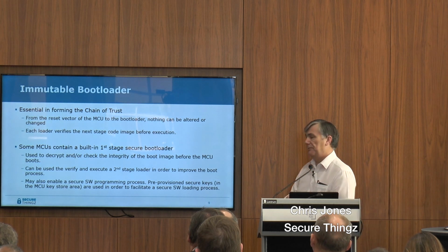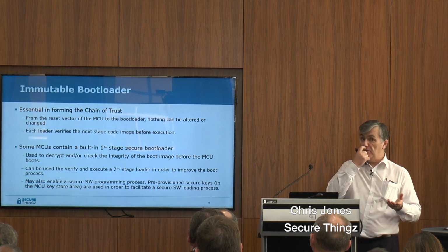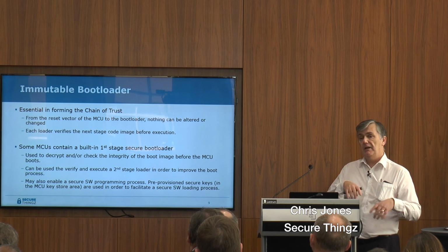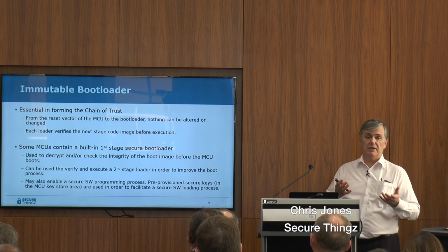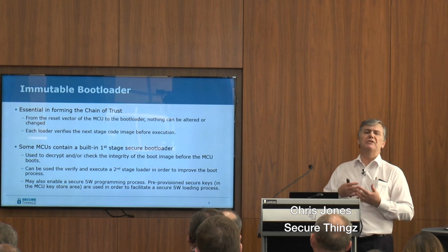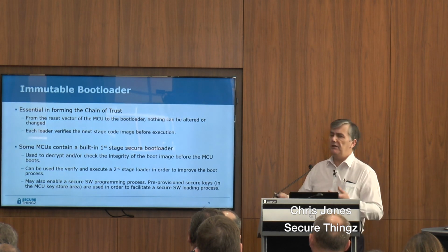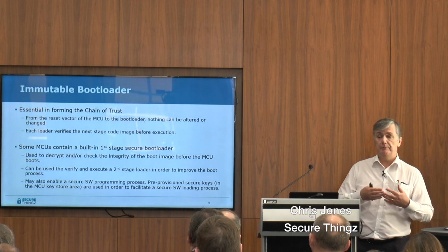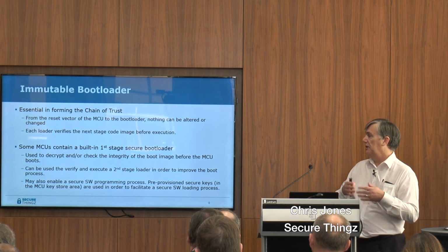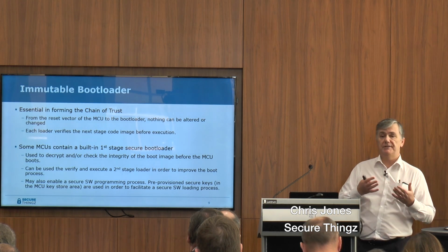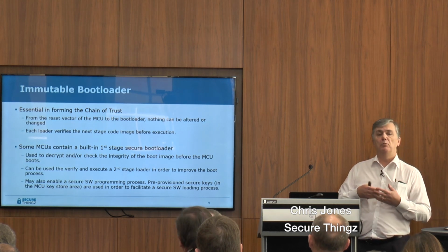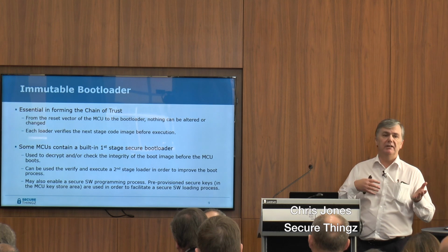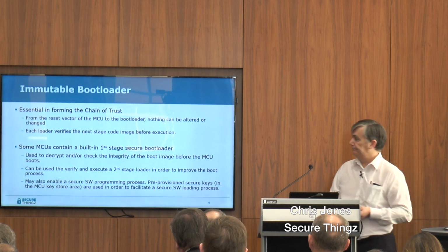So as I said here, sometimes you'll have a first stage bootloader, which will be the ROM version in the device, and then it may jump to a second stage bootloader, which is maybe a more sophisticated manager. So these early ROM-based ones are fairly simple in most cases today. As I said, they just check a hash. So you may want to boot to another more sophisticated boot manager, which can handle updates, handling of keys, etc.